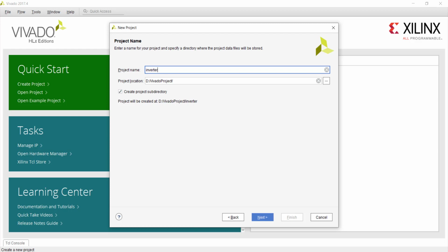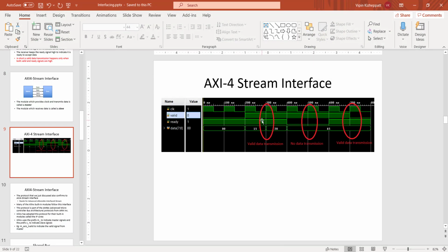What it does is whenever it gets the data, it can be 32-bit wide data. Okay, so what it does is each byte of this 32-bit, so we have total 4 bytes in 32-bit, each byte will be subtracted from the number 255. Okay, so why we are doing it will be clear to you later, because this is a so-called inversion operation